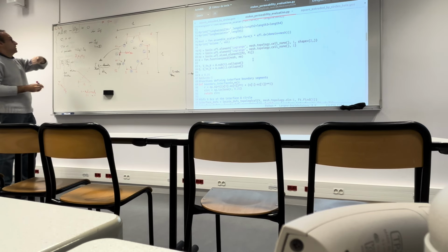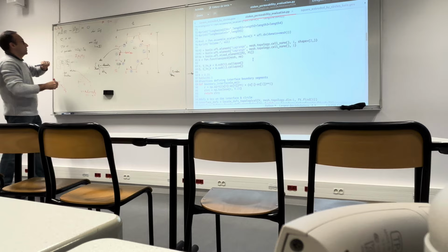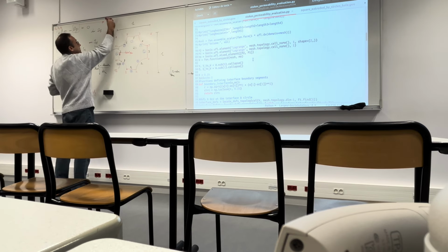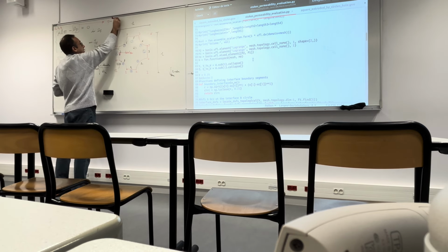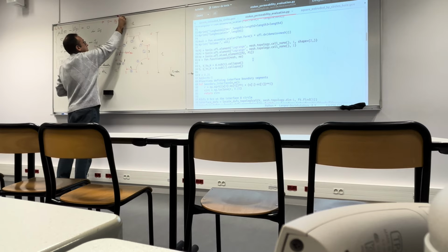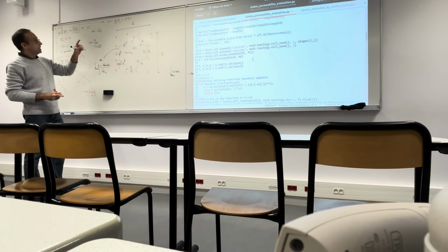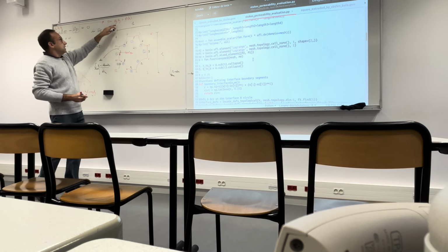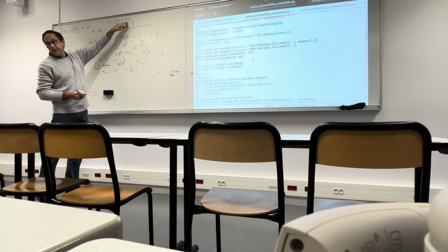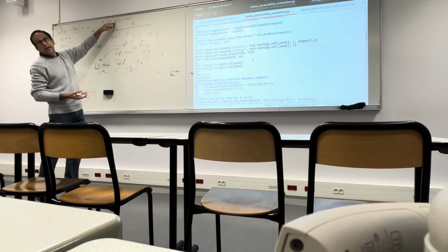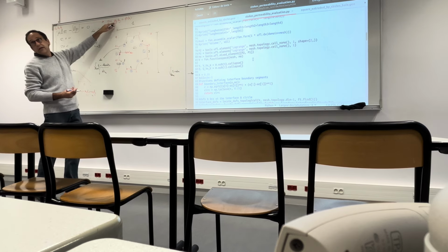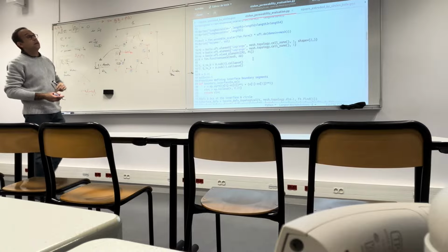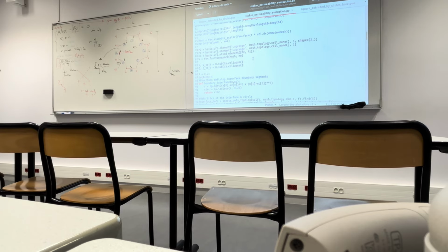In this case, zeta 3 will always be 0. So we wrote P as alpha j zeta j plus phi of zeta, in such a way as to split the two contributions to P: the periodic one phi and the linear one associated to alpha, which is the macroscopic gradient of pressure.